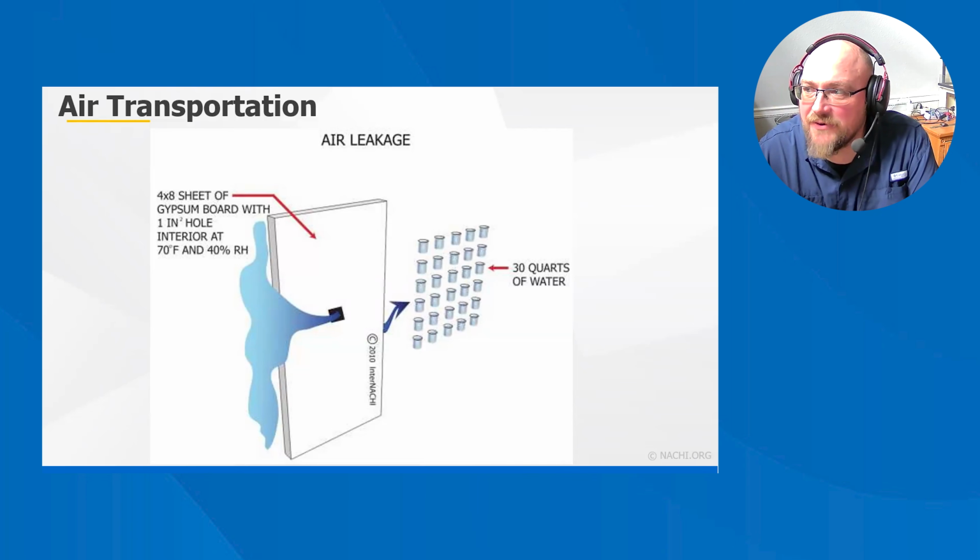The laws of physics govern how moisture reacts within various temperature conditions. The study of moist air properties is technically referred to as psychrometrics. A psychrometric chart is used by professionals to determine at what temperature and moisture concentration water vapor begins to condense. The temperature and moisture concentration at which water vapor begins to condense is the dew point. By understanding how to find the dew point, you will better understand how to inspect for and diagnose moisture problems in a house.